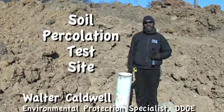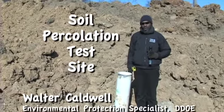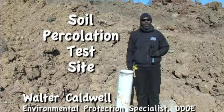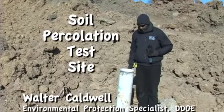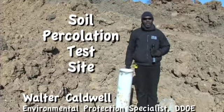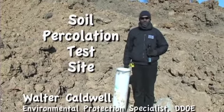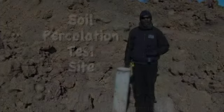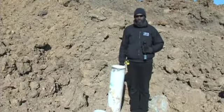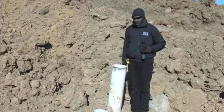Say I got a percolation test site in southeast Washington, D.C., in the Oxon Creek watershed, where infiltration devices have been proposed for the stormwater management practices. This percolation test was conducted on this site right here as part of the feasibility to determine if this type of practice would work for the soils and where the groundwater is, etc. This test was conducted by geotechnical engineers, and they prepare a report for our office along with percolation test results.